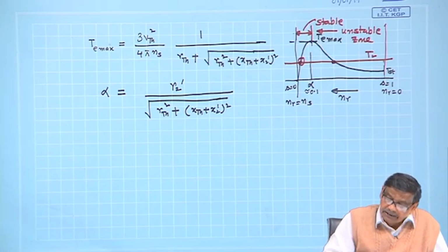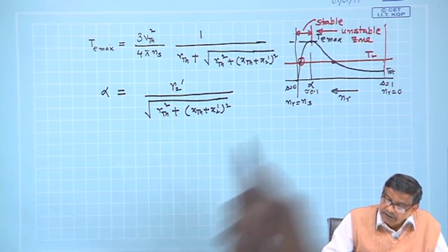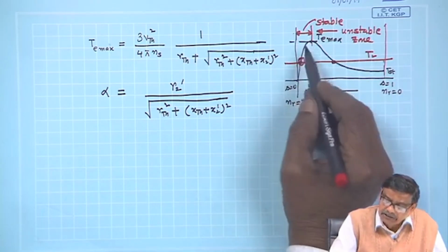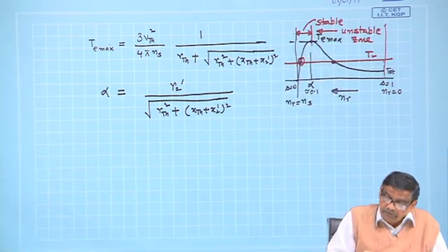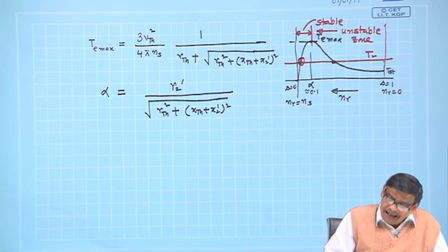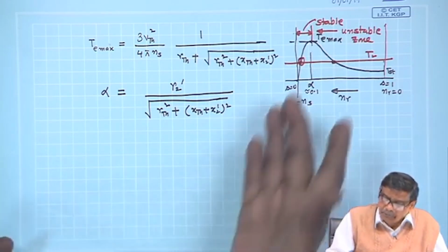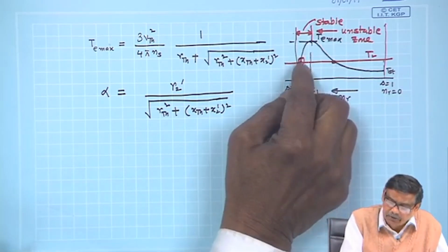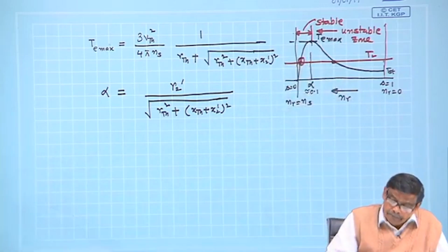And also we noted that the full load torque will be more or less in between, so that you keep enough margin from the line of demarcation between stable and unstable zone, and the full load slip could be of the order of 0.05, half of this is 0.05 and so on.